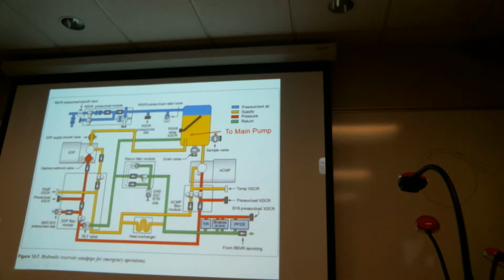You can see that after the fluid gets to the pump, there are a couple of paths the fluid can take. One of them, after the discharge of the pump, is for the supply of normal system pressure. But there's another thing that we'll talk about later when we get into hydraulic pumps. Many of the pumps incorporate a port that provides for what they call a case drain.